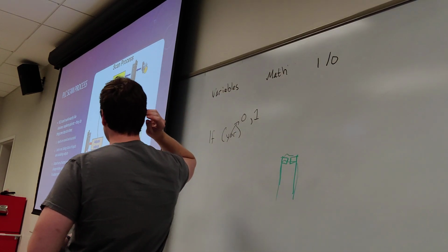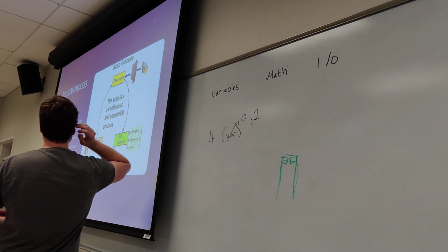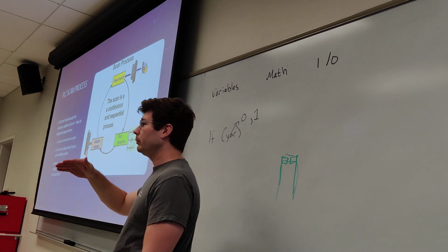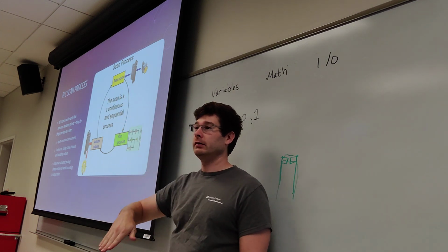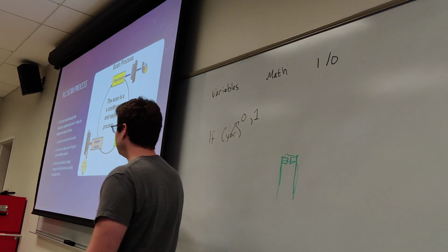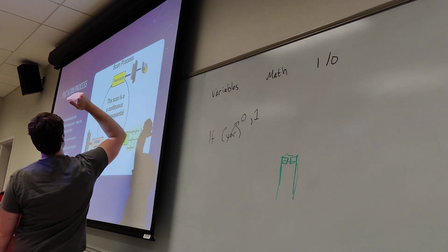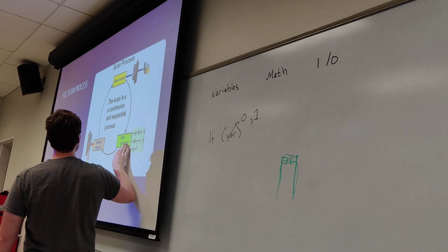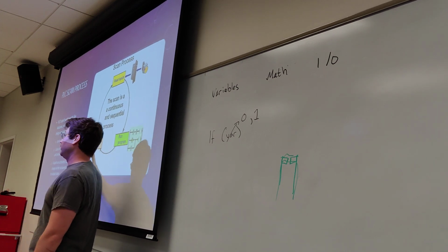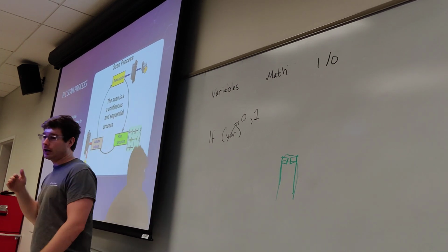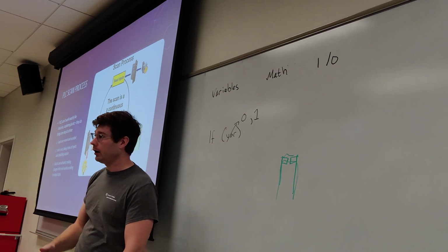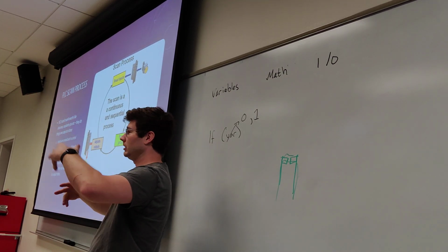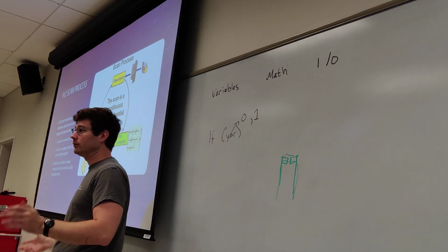PLCs aren't like that. They're very rigidly structured in that no matter where your program says to read an input, for example, it can say it on the first line or on the last line, the input reading step always happens in a defined part of the cycle. It always happens before the program evaluates and before the outputs are adjusted. In a typical computer program, you could write all your outputs, then check your inputs, and then do your processing if you wanted to do it that way for whatever reason.